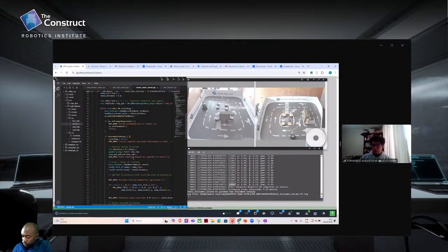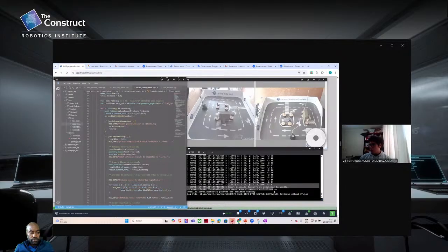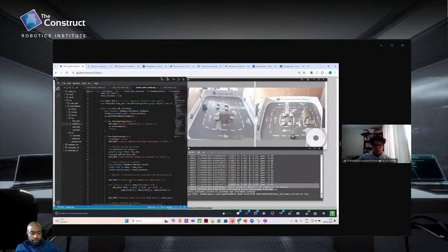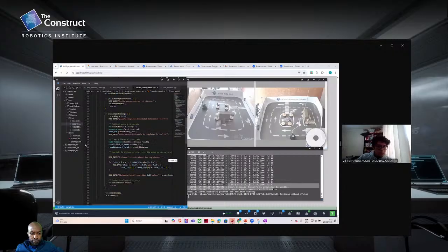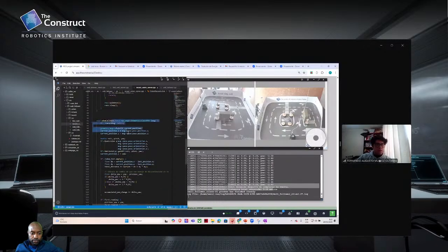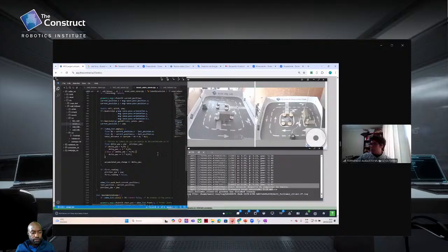Finally, the results are set here. Then I go to the odometry callback function. In this part, it records the robot trajectory, position plus orientation, and calculates the total distance traveled and the accumulated change in orientation, only if recording is active.